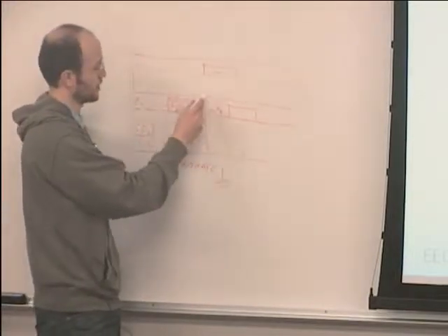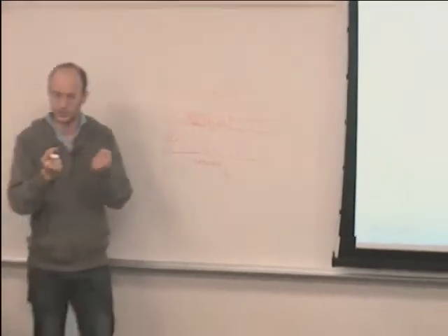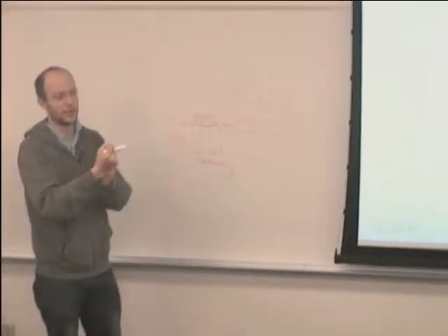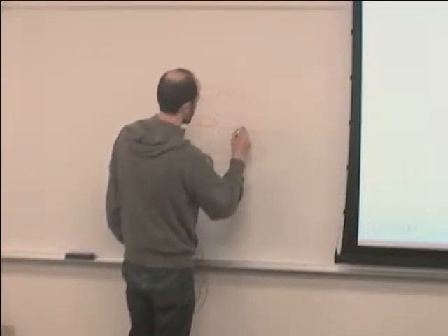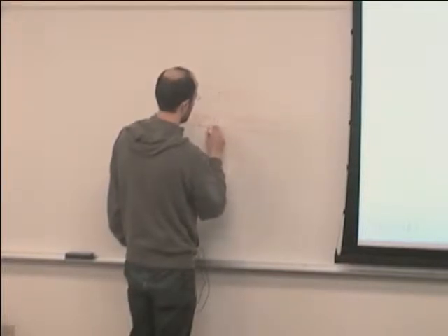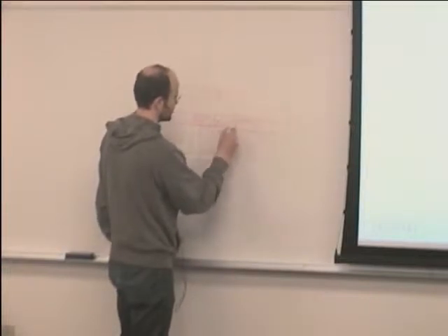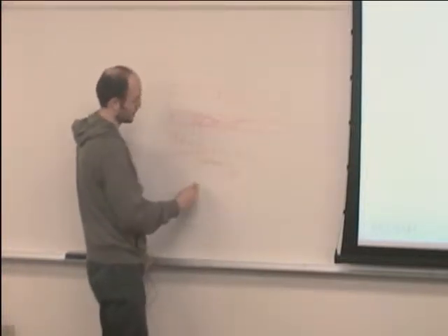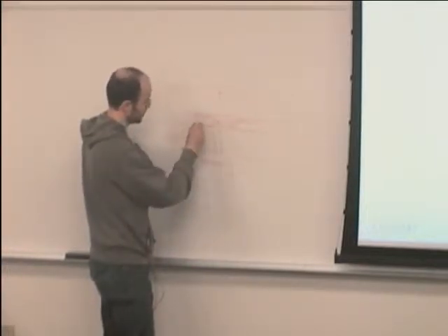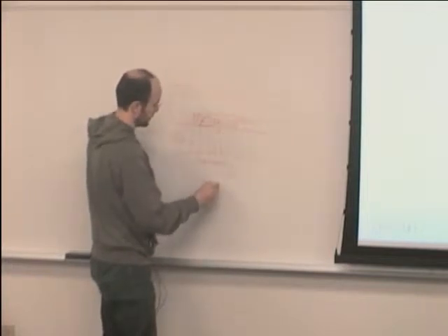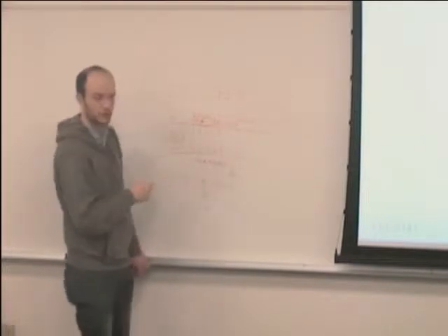So now, this almost never happens, especially in digital, because we try to pack things very closely. And so you always end up with one wire next to something else, okay? So imagine that now you have 2 wires. The electric field lines will not only go towards the substrate, they will also go like this. So there will also be a capacitance, not only between this wire and ground, but between this node that is connected here and this node that is connected here, okay? And if there is a third wire, there will be another capacitance, and so on and so forth.